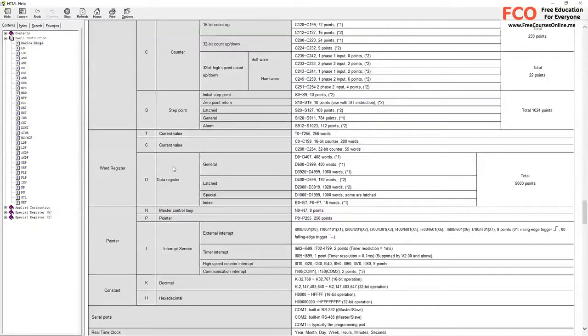Maybe we've got a very specialized machine which must contain some settings like lengths and other sorts of values which we need to do measurements on and comparisons on in our programs to actually cut certain items to length or whatever the application may be. So these word registers are very important in storing our data.